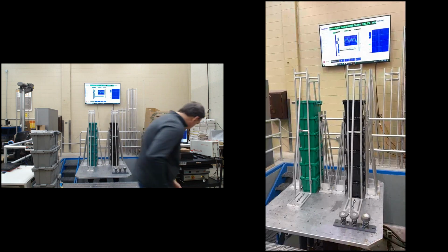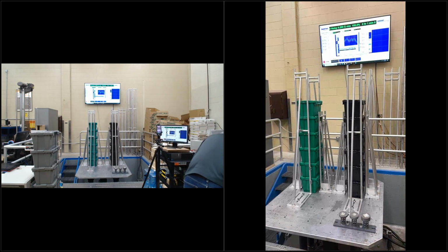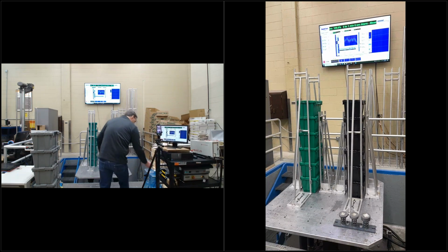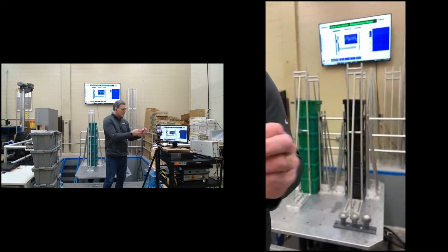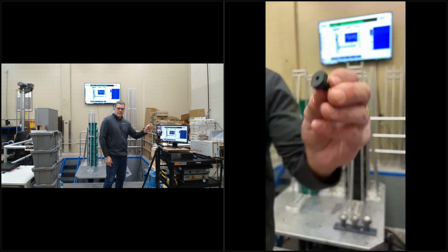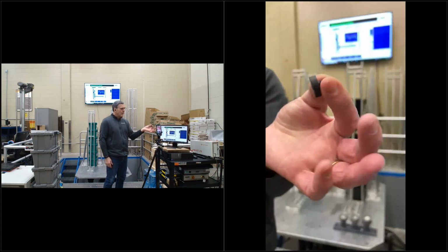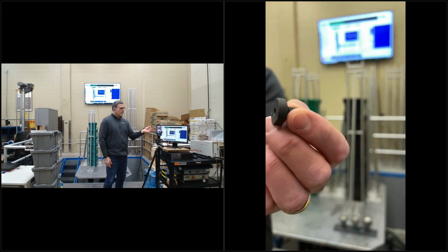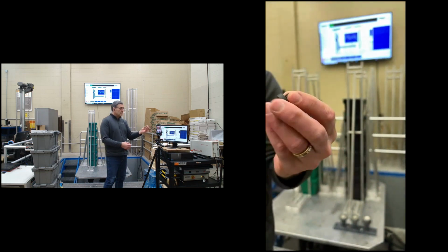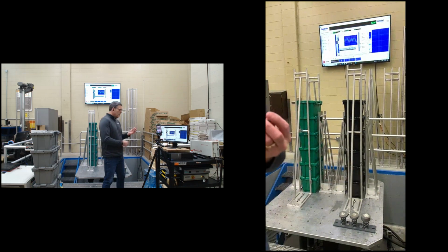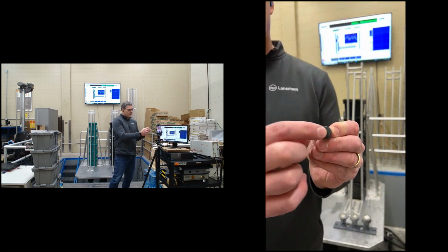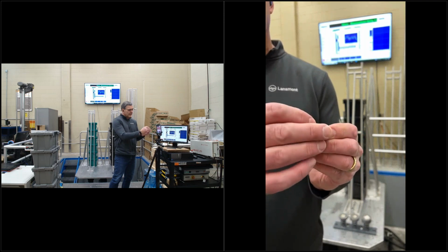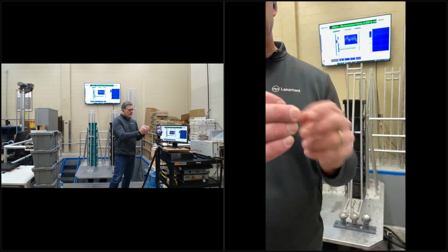See if I can show you it real quick. Where'd you go? Oh, there it is. Now, if you can see this, tell me if you can. Yeah, so you can see I'm holding a little stud in my hand. In this case, it's a Delrin rigid piece of plastic. This stud attaches to our vibration table, and the accelerometer threads into this side of the stud, and then the stud threads into the table.